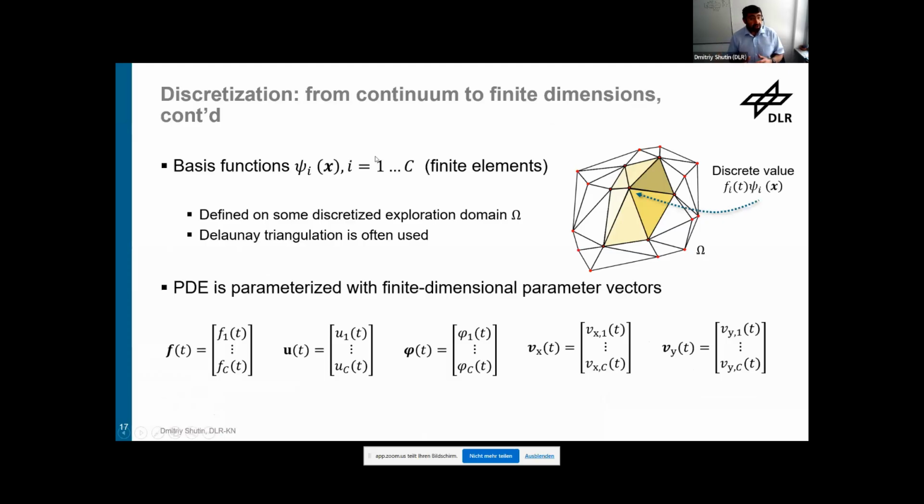And these basis functions that I select, this is something that we call finite elements. So these are functions that are well localized in space. They have effectively 1 at one particular node in space and 0 everywhere else. So they are orthogonal in space. And if you create these functions, then what you typically get is this classical mesh type discretization, where one of these finite element functions you see here is shown in color.